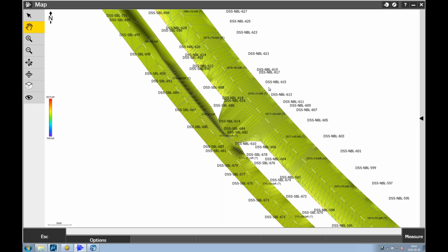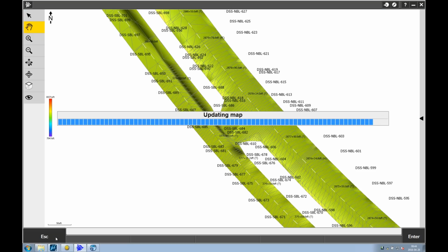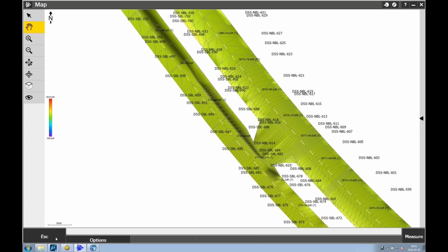So I have this data in here. The one piece I don't have pulled up on here, but I do have available if I need it, is this original ground model that I can use to verify any of my original terrain in the field if I've got any issues on it. So at this point, I've got my road models with side slopes in them, my design slope stake points. I'm ready to go out and do my slope staking and grade checks from there.